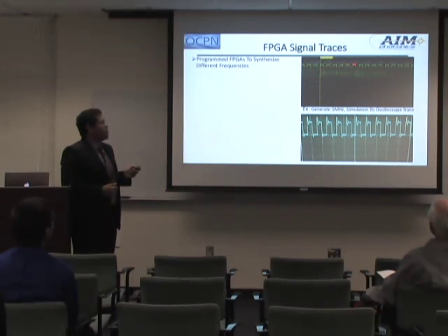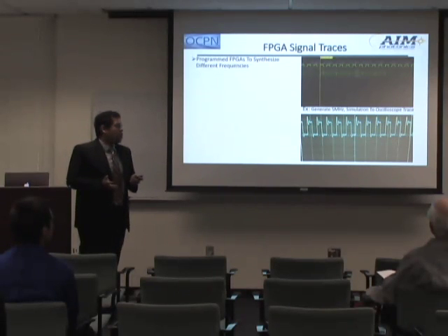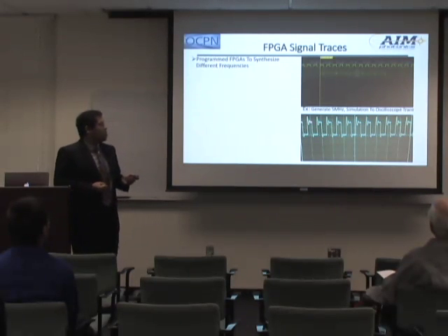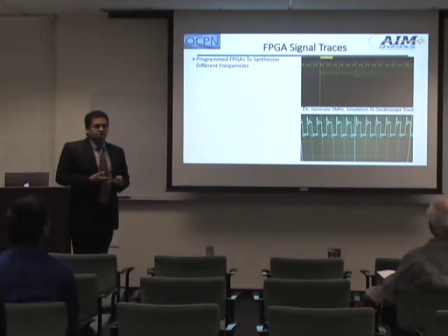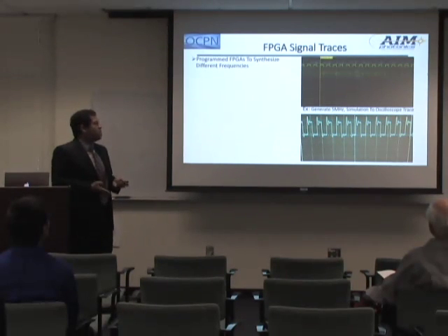Using a 100 megahertz frequency clock reference, I've been synthesizing in this example a 5 megahertz signal. This is the simulation. The process goes from writing the code to simulating it, to then assigning it to the FPGA and connecting that to an oscilloscope to determine just how well the code translates to the actual hardware. This is the oscilloscope trace of this simulation. It looks a little different, but they are both 5 megahertz waves. So the process has been done from beginning to end.